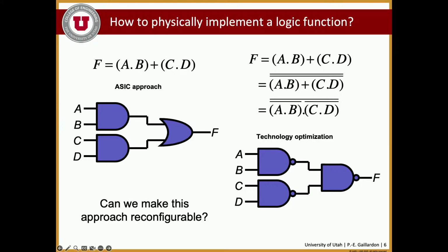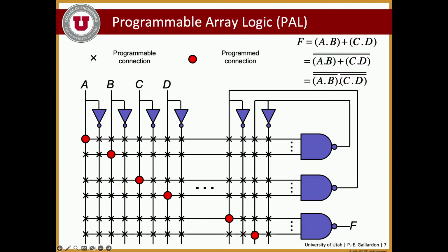Well, an initial approach that was developed prior to FPGA, so the ancestor of reconfigurable logic, was the programmable array logic. Now, here's the idea, right, of a PAL topology. You're going to have fixed logic gates, and what you're going to do is change the configuration, so change the way you wire the inputs and the signals into these logic gates. And to do that, so you had these wide arrays of connections, and you could use memory to program a conductive path between, let's say, input A and that line, right? So you had to configure each of these elements either being off or being on.